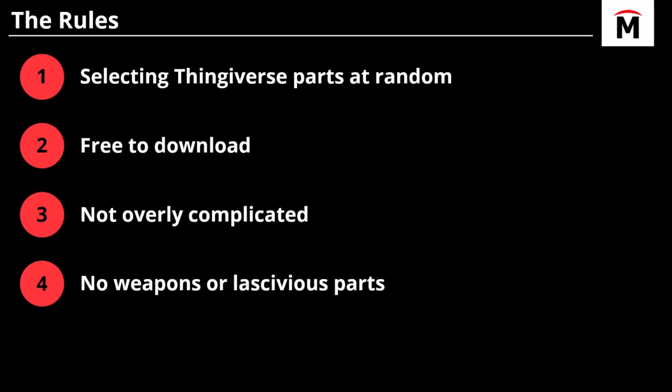Now, the third rule really applied for FDM printing, because with FDM you have to really plane cut. You got to really mess around with stuff in CAD, especially if you're dealing with a part with a lot of complicated geometries. And so I put this rule in here. Let's look at parts that are fairly basic. Let's not do anything too complex, because it can bog down the slicer.